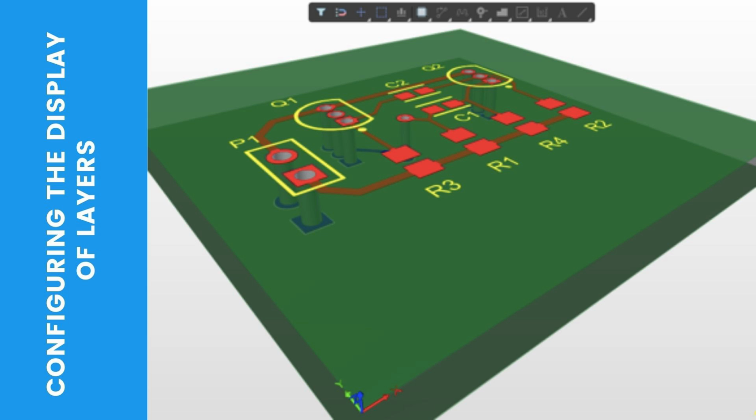Your view of your board is a bird's eye view, looking down the Z-axis into the board from above. The PCB editor is a layered design environment. The objects you place on signal layers become copper when the board is fabricated. The strings you place on the overlay layers are silkscreened onto the board surface, and the notes you place onto the mechanical layers become instructions on the assembly drawing that you print.